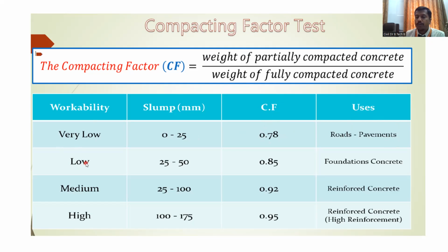While the concrete with low workability, that is from 25 to 50 mm, the compaction factor will be in the range of 0.8 to 0.85. These are some standard cases I have taken. Such concrete you can use in the foundations, PCC bed.